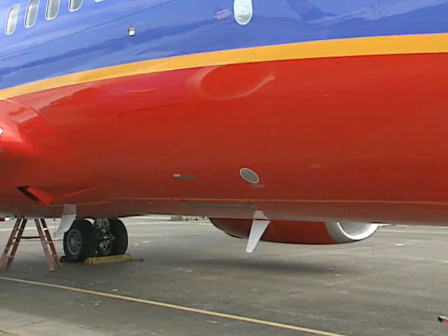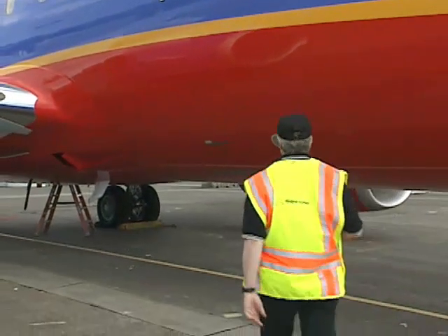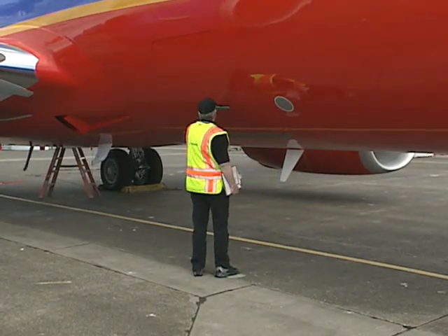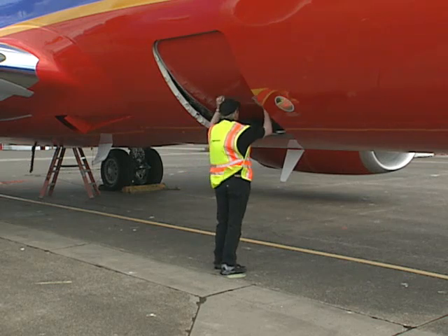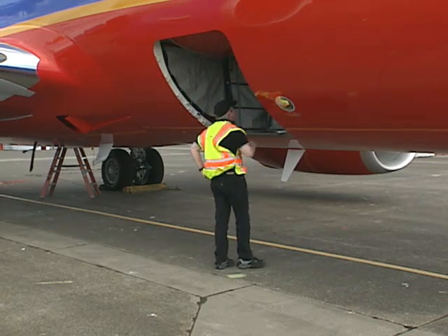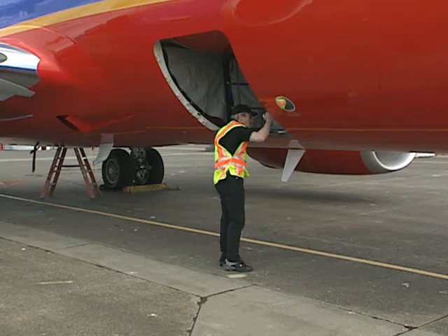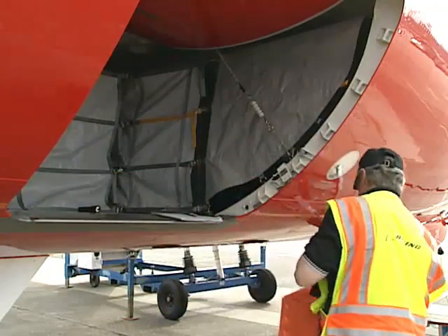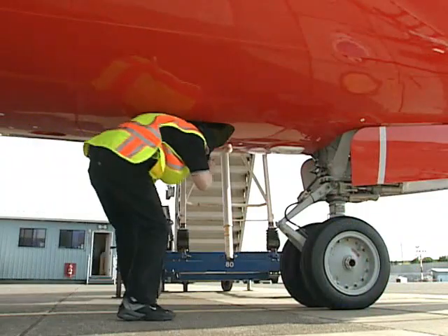Prior to any weighing, an inventory must be done. Our goal is to configure the airplane's contents as closely as possible to the basic empty weight configuration defined by the inventory list. This means removing any items that are not supposed to be on the airplane according to the list, replacing any items that are missing according to the list, and documenting any differences that cannot be corrected. Let's begin at the door by checking the cargo compartments.